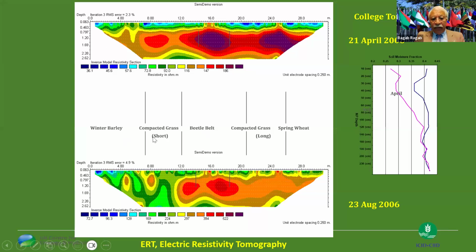Also under different vegetation, as the water uptake by different vegetations differ, and then you can really see how different vegetation, especially during the drought periods, which vegetation survives better than the other. And also you can identify which soils in the drought can supply water better than the others. And we discovered the chalk soils in the UK can supply water longer than the clay soils when you have a drought period.